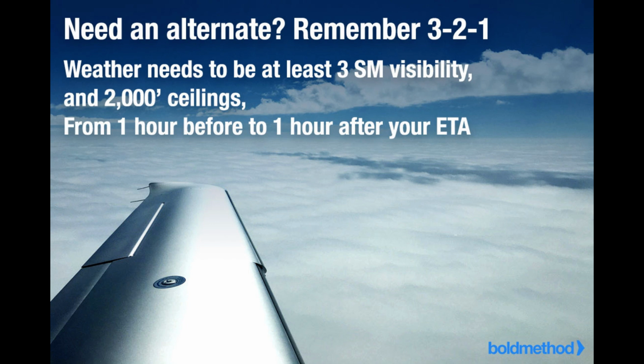Though the pilot is the final authority for the flight and ultimately has full responsibility, the dispatcher is responsible for creating flight plans that are accurate and comply with the CFRs. Alternate minimum criteria are only used as planning tools to ensure the pilot in command and dispatcher are thinking ahead to the approach phase of flight. In the event the flight would actually need to divert to an alternate, the published approach minimums or lower than standard minimums must be used as addressed in op specs documents.